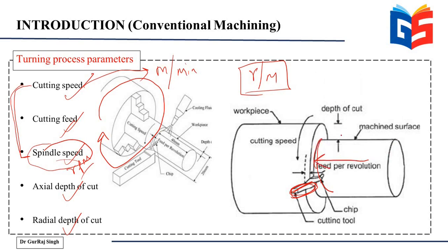So you need to reduce the diameter. You're going to move the tool from here and start moving it to the left, so as you keep on reducing the diameter till the end, or till whichever point you want to reduce it.